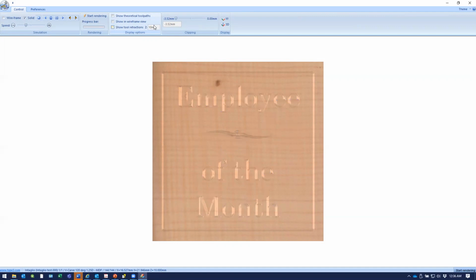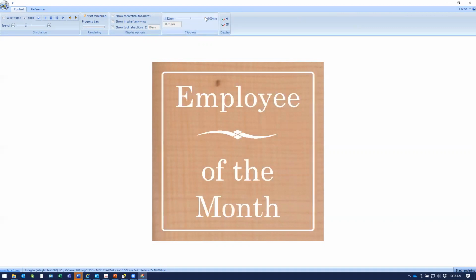Okay. I also can look at the clipping, and basically what the clipping does is as I slide the clipping, I can see some white areas appear. So the white areas that appear first, like in the design in the center, those are the deepest carvings in the material. So in order to get the line weight to show the width here, it sank the cutter deeper in. So this will give me an idea of what areas are going to be carved deeper, wider lines, versus what areas will be more petite carvings, like the thin contours of the Y.